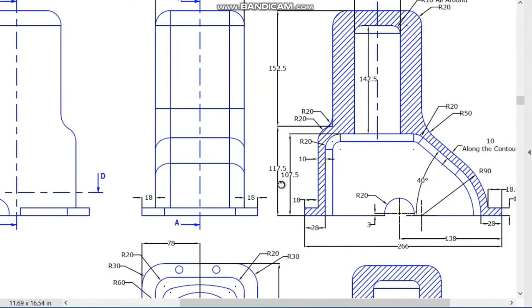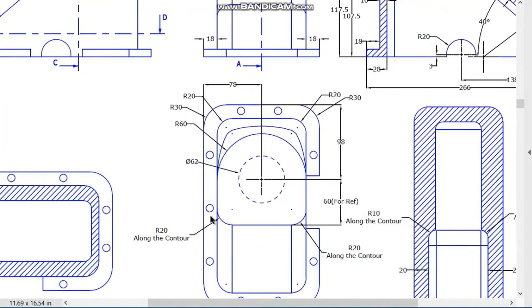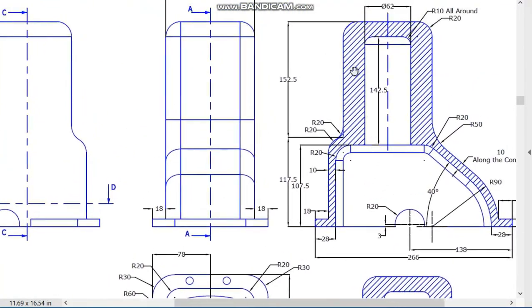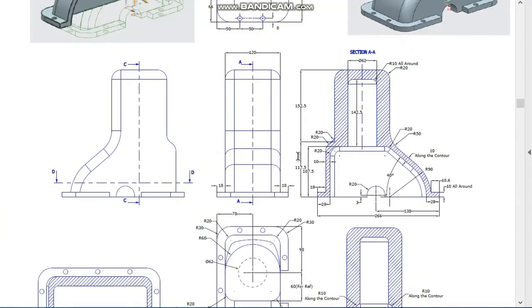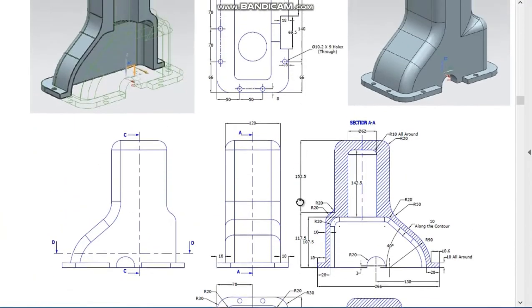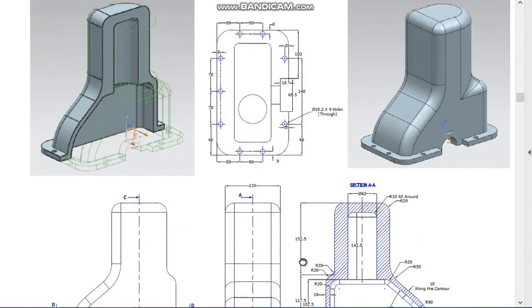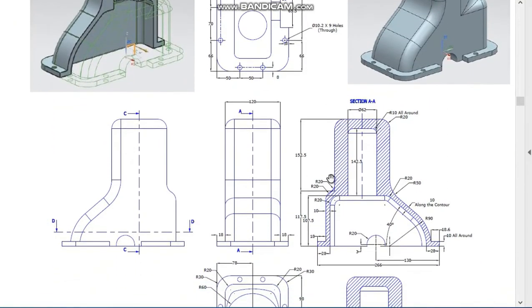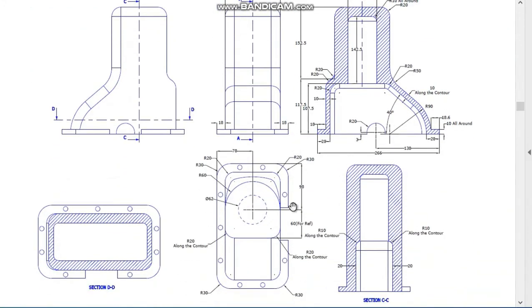So at this height you will create this particular section and you will move down by using pad. It will create a solid body, and then go for cutting of these internal sections. Don't worry, I am there for you. If you require any help in developing the model for this and the drawing study, you can get back to me with your doubts and I'll solve it.